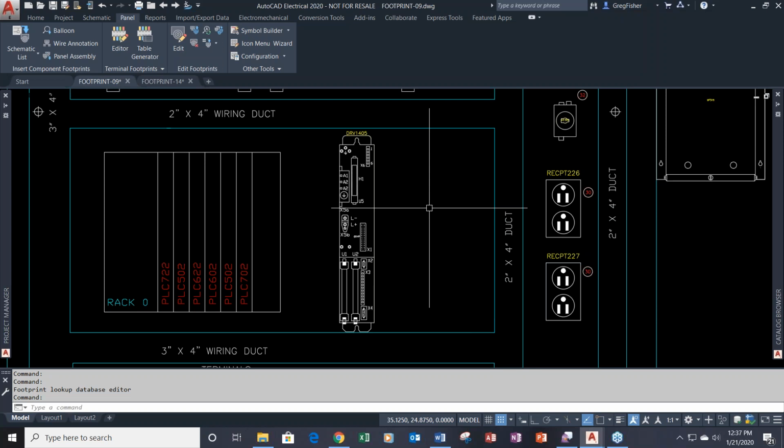You have to link that footprint symbol that you created to the part record in the parts database. So obviously you have to add the part record to the parts database first. So four-step concept: you get a brand new component in right off the shelf, got to create the schematic symbol, got to create the footprint symbol, got to add the part record to the parts database. You link the two of them together, everybody's happy.